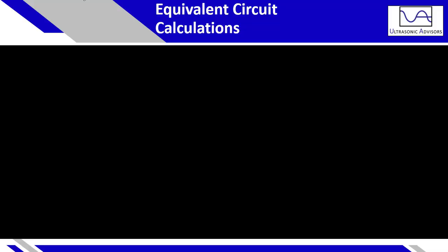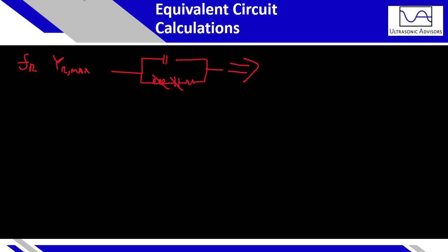So at that frequency, at FR, the real admittance is at its maximum, we have our inductor and capacitor canceling out. So what you're going to be left with is just your parallel capacitor and your resistor here.